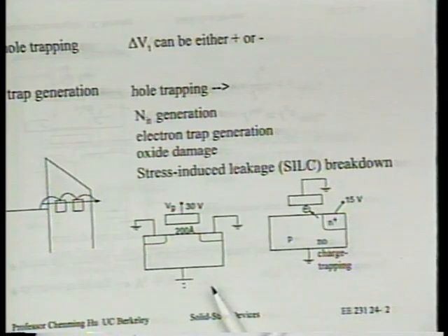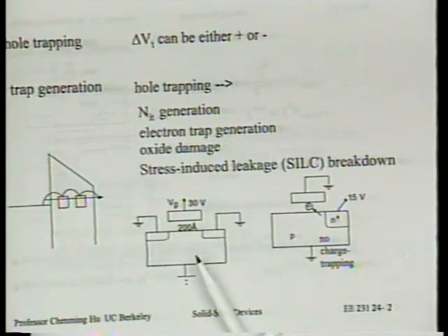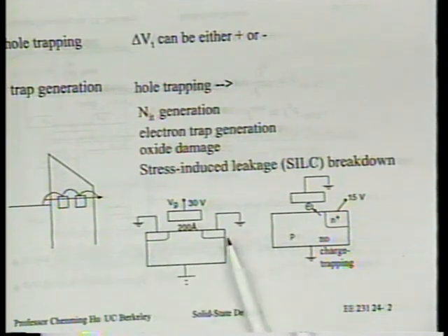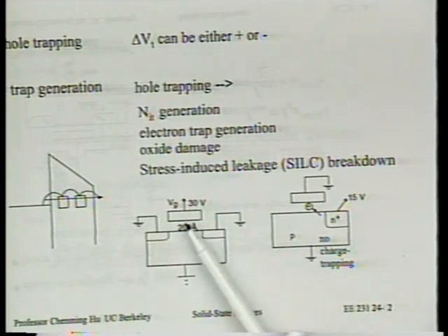I'll let you think about this situation. Let's say we take a transistor. I arbitrarily use 200 angstrom as an example because that is when I first encountered this situation. Let's say 200 angstrom of oxide. Now suppose you ground the source, ground the drain, and ground the substrate. So the body is all at one potential now. You only apply a voltage to the gate. You ramp up the gate until this oxide breaks down. It's a way of measuring the oxide breakdown voltage.